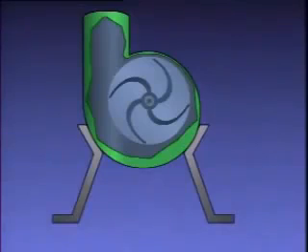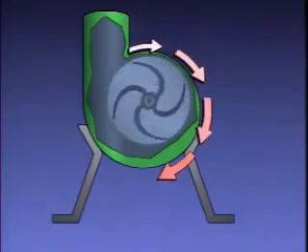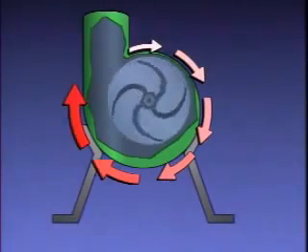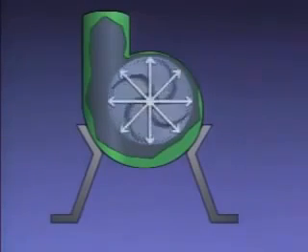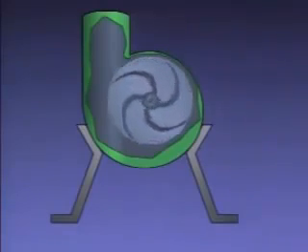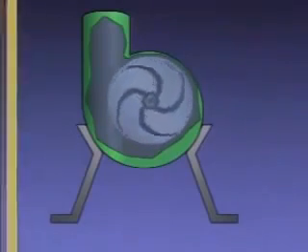No matter what type of impeller a centrifugal pump uses, the liquid being pumped gains pressure as it slows down to fill out the increasing volume of the volute. Radial thrust is a type of thrust that tends to move a pump shaft perpendicular to its axis. In a pump with a volute, the thrust is created by the difference in pressure across the volute.